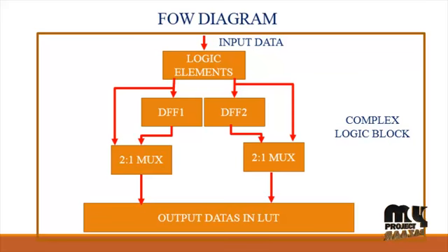Generally, a logic gate is an elementary building block of a digital circuit. Most logic gates have two inputs and one output. At any given moment, every terminal is in one of two binary conditions, low or high, represented by different voltage levels. The logic state of a terminal can and generally does change often as the circuit processes data. In most logic gates, the low state is approximately 0 volts, while the high state is approximately 5 volts.